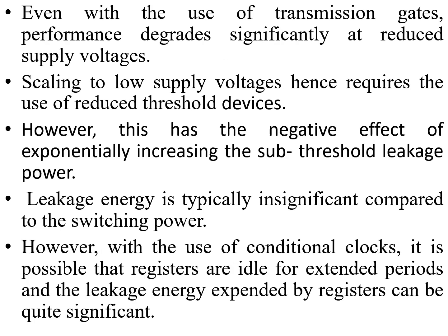Even with the use of transmission gates, the performance degrades significantly at reduced supply voltages. Scaling to low supply voltages as a result requires the use of reduced threshold devices. However, this also has a negative effect: it exponentially increases the sub-threshold leakage power, though this leakage energy is insignificant when compared to the switching power.